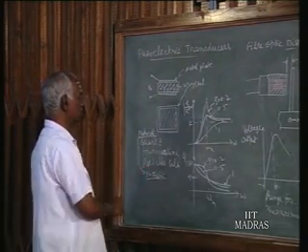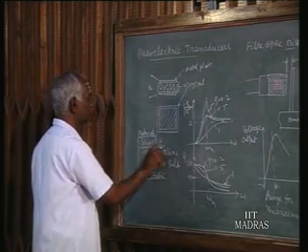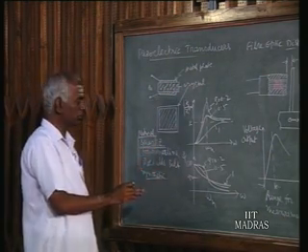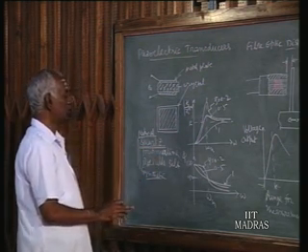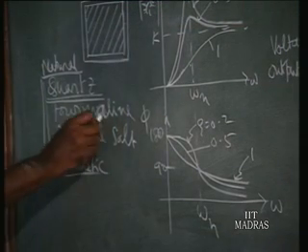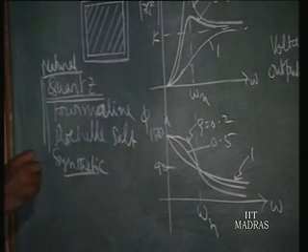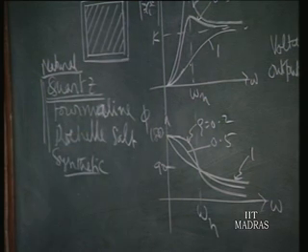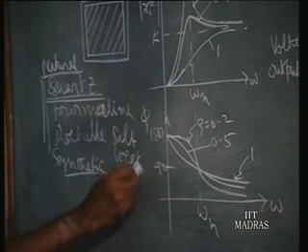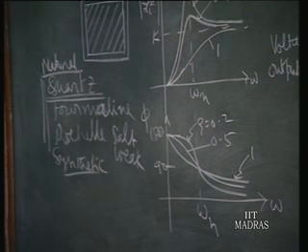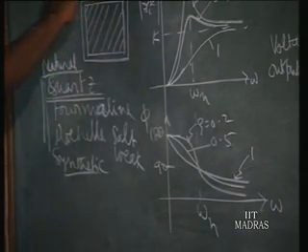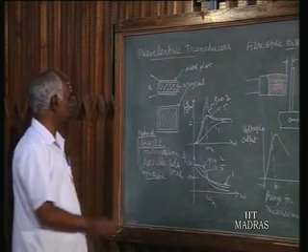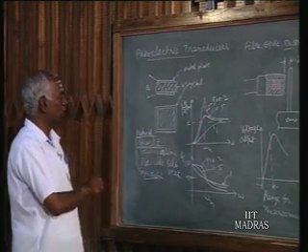Among these three crystals, quartz is very often used. It is because it has moderate vibrations, is cheap, and is available. Whereas tourmaline gives very small vibrations but is very strong, and Rochelle salt has a very large amplitude of vibrations but is very weak. So quartz gives moderate vibrations, is cheap, and is available. Hence wherever we go for piezoelectric crystals, we conveniently select quartz crystal, unless there is a demand otherwise.